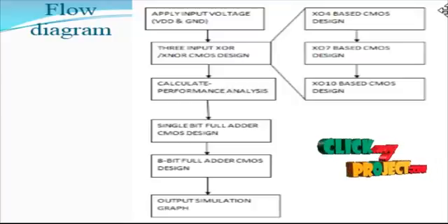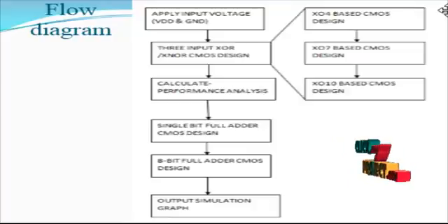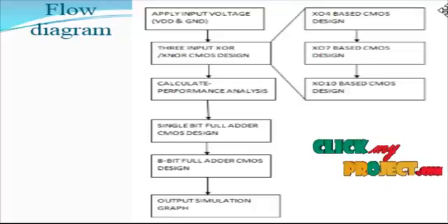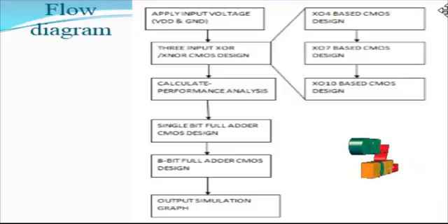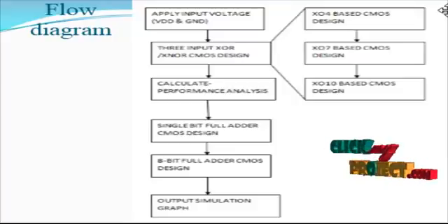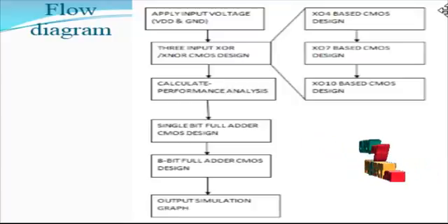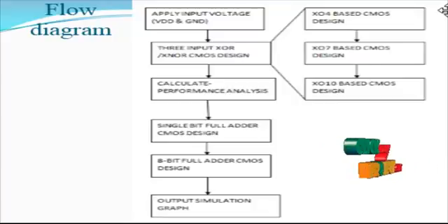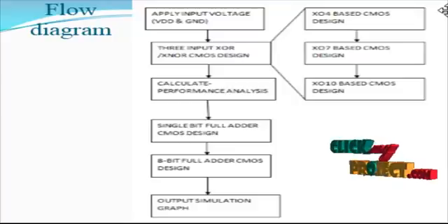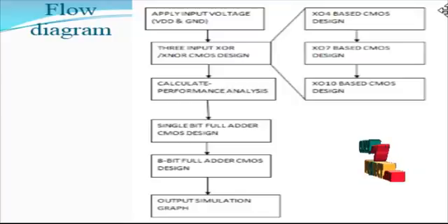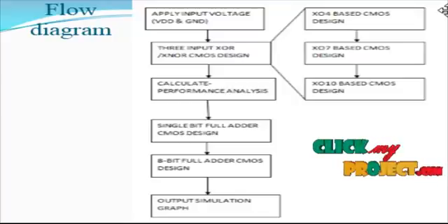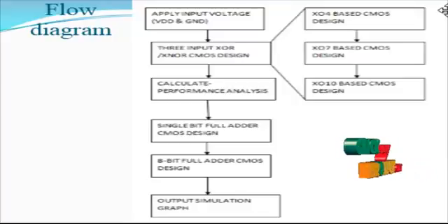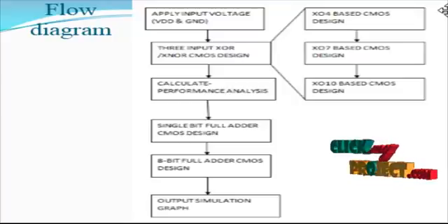So we place this CMOS design in our adder circuit to improve the adder performance level and to improve the single bit and 8 bit full adder sum and carry output generation. This sum and carry output is full-swing for our output variations, reduces the leakage power, and also reduces the overall power consumption compared to the conventional ripple carry adder, and produces the Kogge-Stone adder structure to implement our 3 input XOR based X04 based CMOS design.